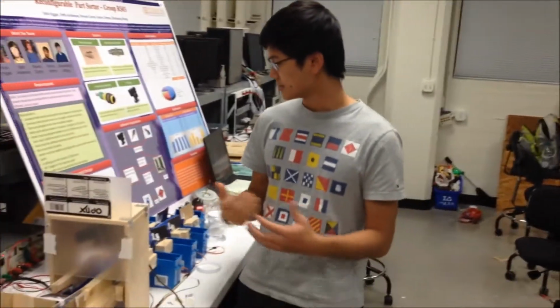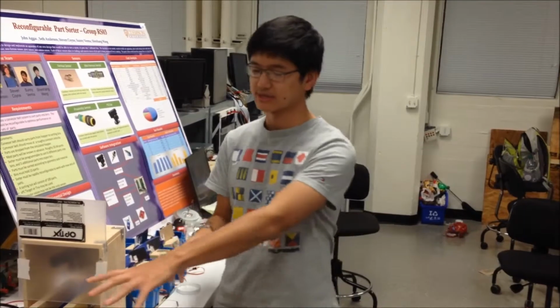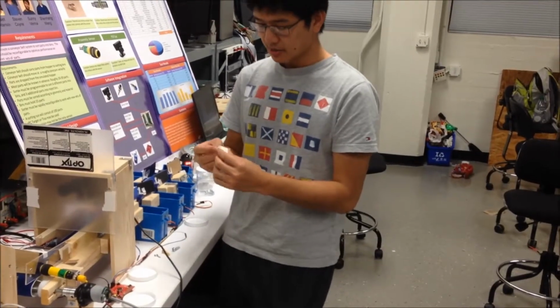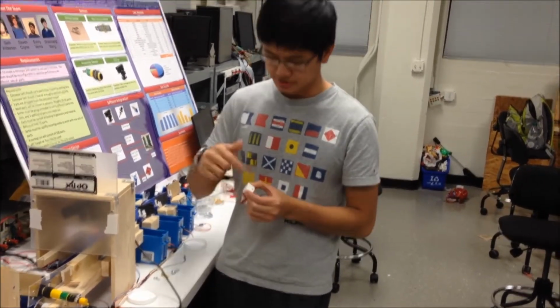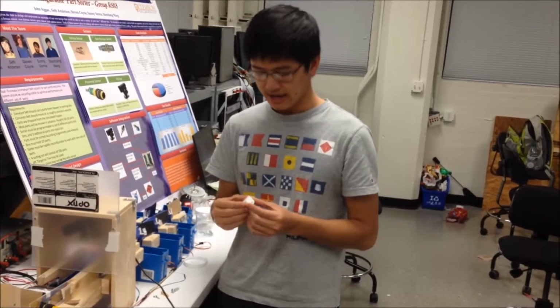Now, our C code that controls our camera is stripped down and, once it receives the image, will take just a single image capture, very, very efficient code. When it processes this one image, it looks for the contour around the image, and once it finds that contour, it takes several different statistics. It finds the perimeter of this contour, it will find the area of the image in this contour, and it will also calculate the area to perimeter ratio.